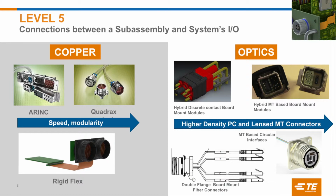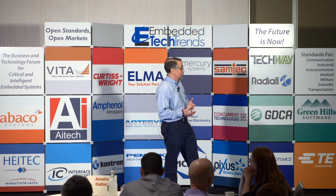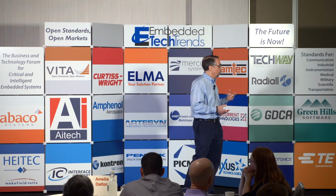If you move to level 5, what you see is the trends in copper have taken advantage of the speed and modularity of some of the standards like ARINC and others. And there are now copper solutions both on the cabling side and on the contact side that let you increase speed and do things like run gigabit Ethernet over these connections from the boards to the backplanes. And you can use high-speed laminates and copper rigid flex combinations to route electrical signals high speed to the cards, from the cards rather to the back to the I/O panel.